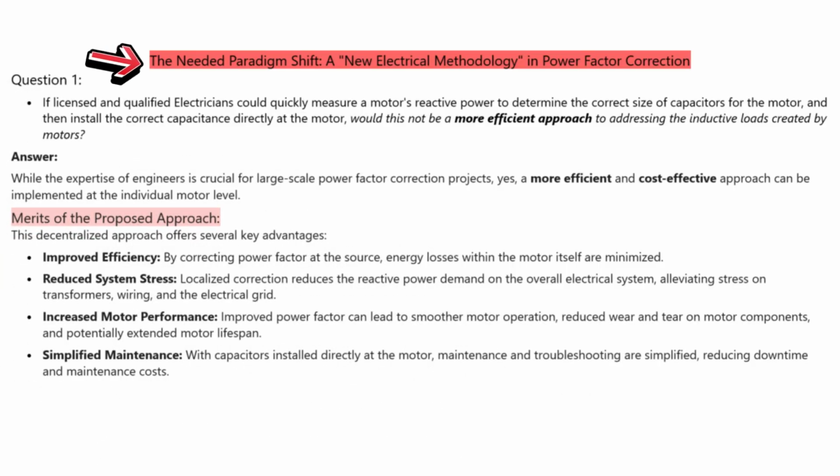The needed paradigm shift. A new electrical methodology in power factor correction. Question 1. If licensed and qualified electricians could quickly measure a motor's reactive power to determine the correct size of capacitors for the motor, and then install the correct capacitance directly at the motor, would this not be a more efficient approach to addressing the inductive loads created by motors?